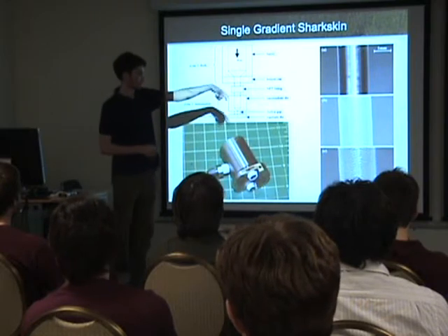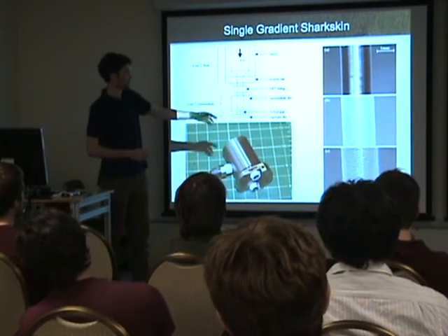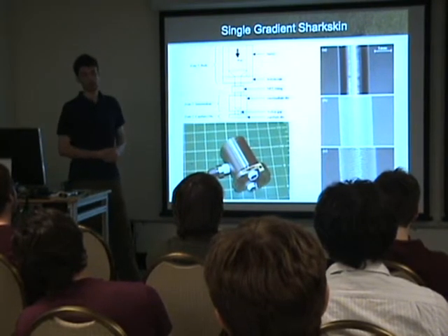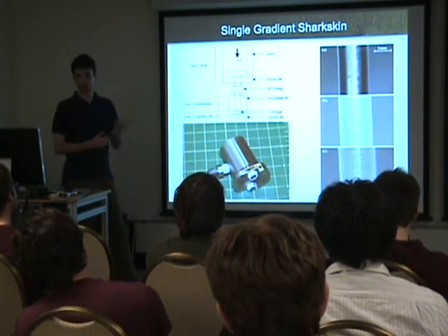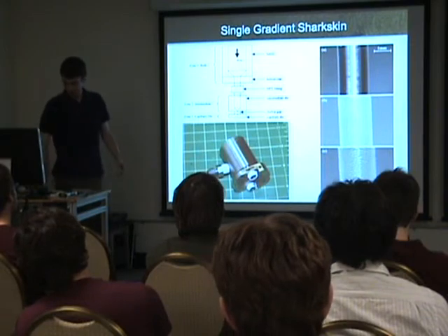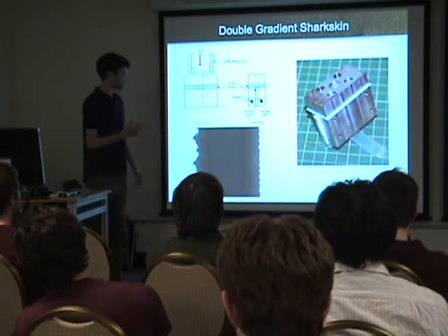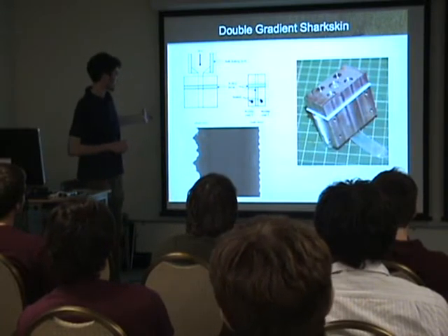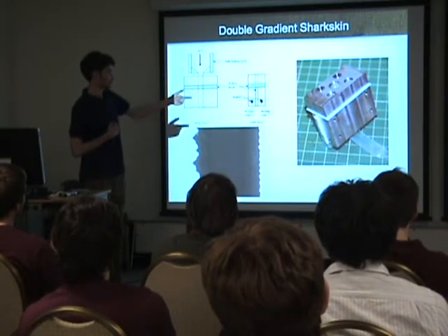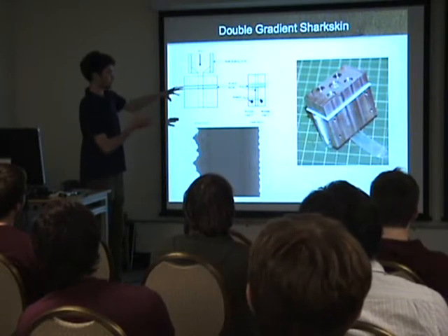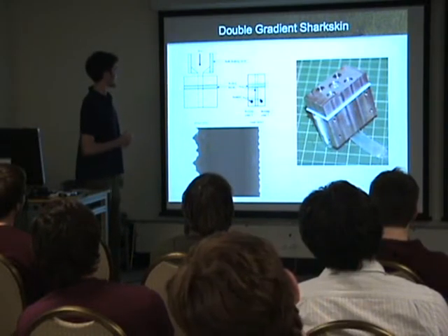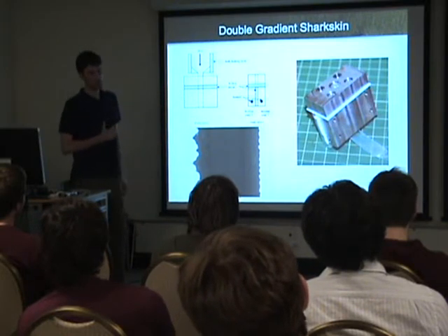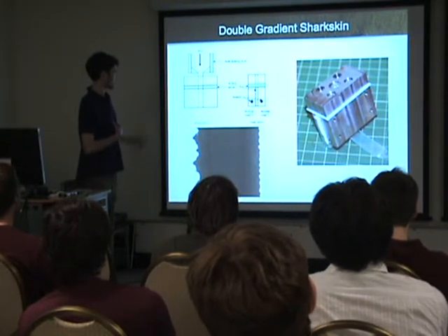We can see here cylindrical sharkskin of varying degrees, and the difference in sharkskin magnitude is created by the difference in temperature gradient between your bulk flow and your output plane. So moving forward, the next step is to say, well, okay, we can do that in one dimension. How about two? We've got two different gradients on either side of a square die, this stainless steel looking chunk, where you've got two heaters, two different heating implements, and it's the same technique more or less.